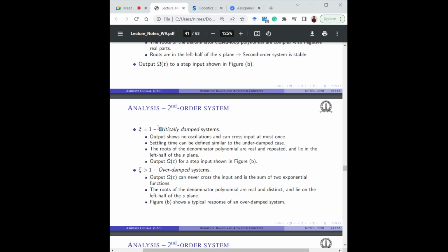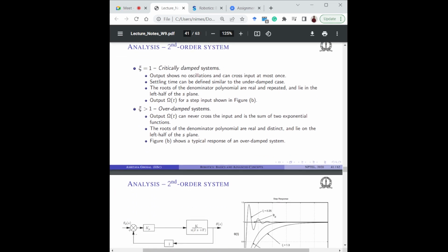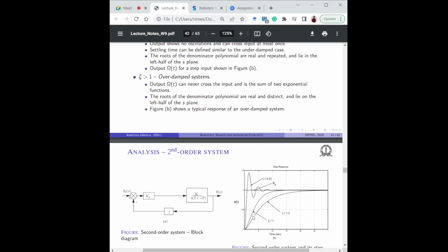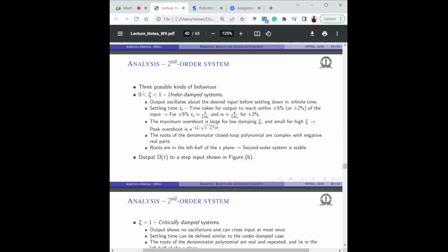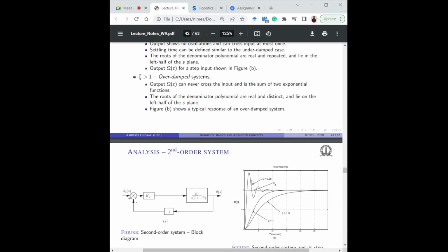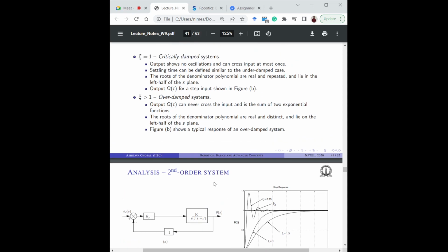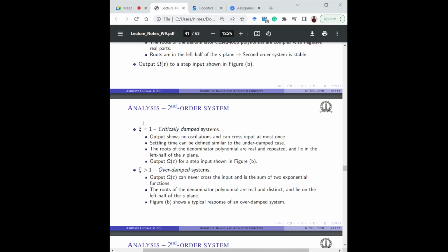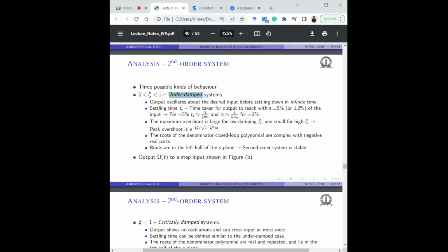So what is the difference between critically damped and overdamped? The critically damped response is the response that reaches the desired state fastest without any overshoot. Without any overshoot, it will converge, or go into an acceptable error range, fastest as compared to the overdamped version. And if you allow for overshoots, that is, if you make your system underdamped, that will introduce some overshoots, but it will also cause your system to settle much faster as compared to the critically damped and overdamped responses. So you can design your systems to be critically damped, overdamped, or, if you can allow some overshoot, underdamped as well.